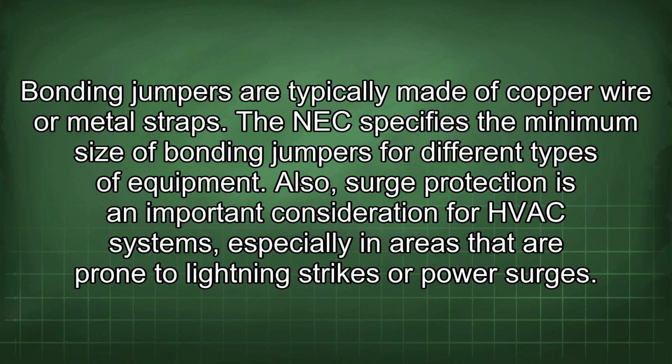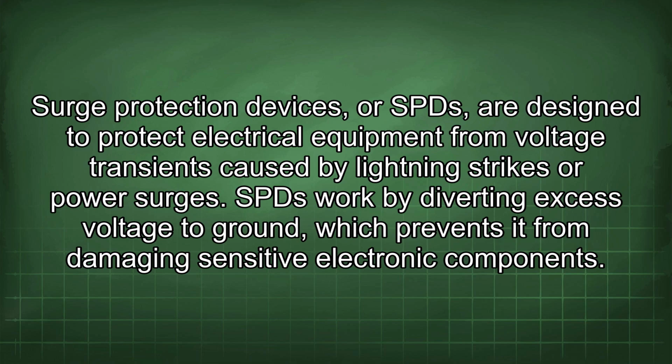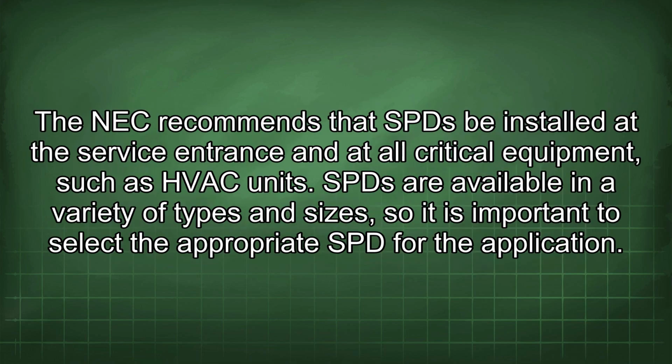Also, surge protection is an important consideration for HVAC systems, especially in areas that are prone to lightning strikes or power surges. Surge protection devices, or SPDs, are designed to protect electrical equipment from voltage transients caused by lightning strikes or power surges. SPDs work by diverting excess voltage to ground, which prevents it from damaging sensitive electronic components. The NEC recommends that SPDs be installed at the service entrance and at all critical equipment, such as HVAC units.